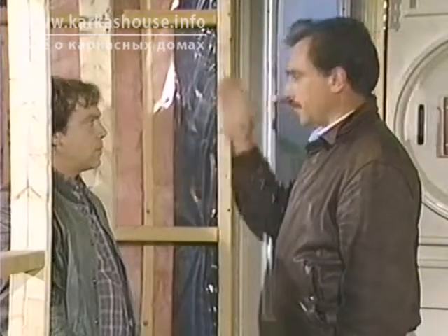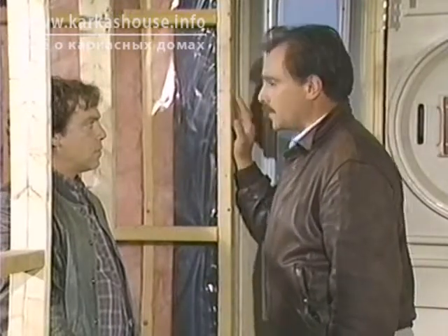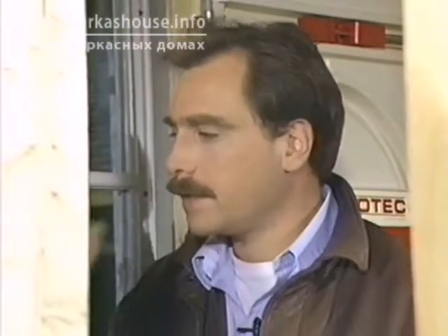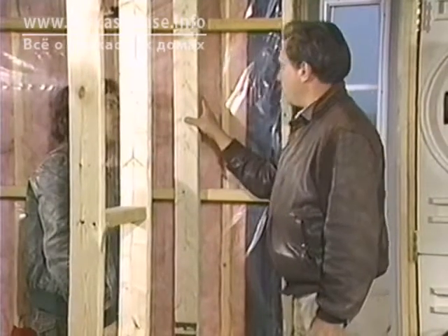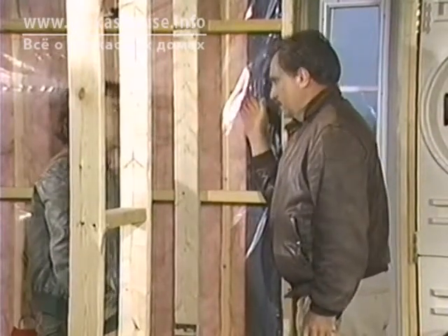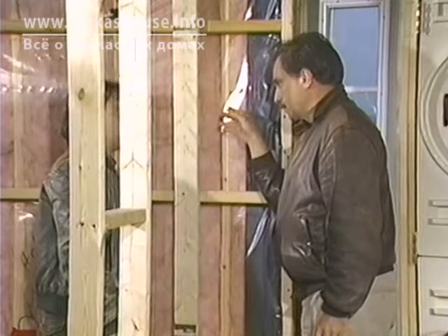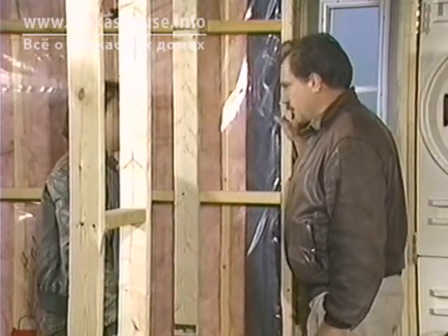Well, the smoke seems to be just drifting up on its own, but not because there's any wind coming in. Sure isn't. The reason for that is because we've very carefully seen this poly barrier put in throughout the entire building. Goes up the walls, across the ceiling, everywhere. The builder has very carefully detailed it, for example, around partition walls here, where you can see that the poly has been run right through, and the wall has actually been installed after the poly has been put in place in this particular situation. All the doors and windows have been wrapped.